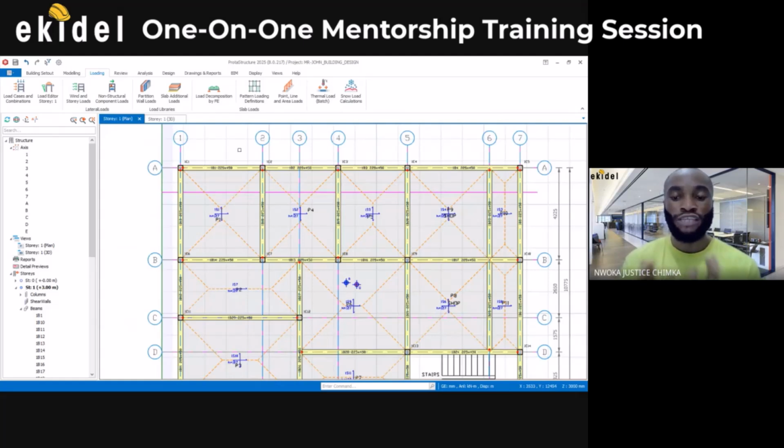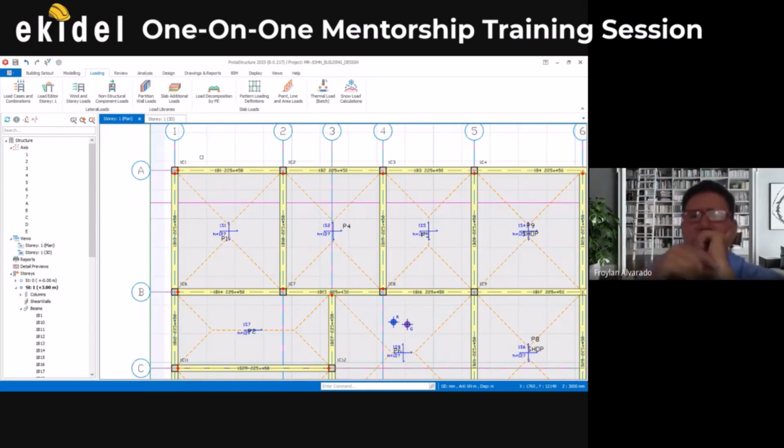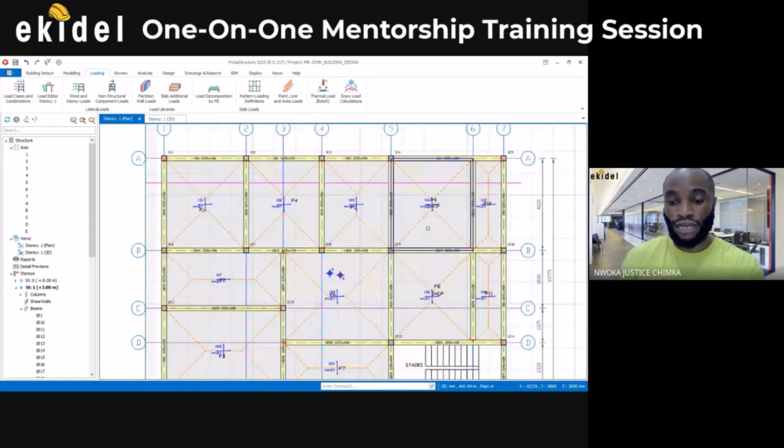So before you insert story, you want to make sure that you are done with everything, because once you insert, it's like copying what you have on the ground floor to the upper floor. If you don't hinge it now and then insert, you have to pass through this process twice: hinge the ground floor, then the first floor, which will take a longer time. So make sure you are done with all the changes you are meant to do, and then you can insert story.